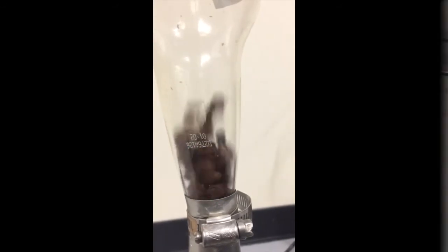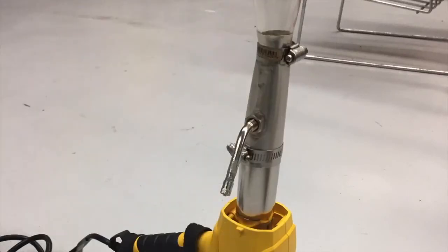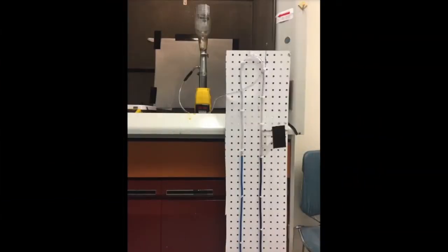The next design consideration was for the pressure drop, which was an important metric in understanding the correlation between pressure drop and mass loss for the fluidized bed. Furthermore, to connect to the outlet, we used a manometer made with tubing and water and food coloring to be able to measure the pressure drop, because with a manometer you can use the height differential to see the pressure in inches of water.